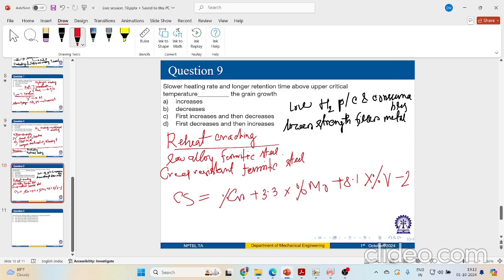You got it? Initially it was dissolved at high temperature, and when you cool, there is not enough time for carbides to reprecipitate, resulting in supersaturation of these alloying elements as the austenite transforms into martensite if hardenability is sufficient.